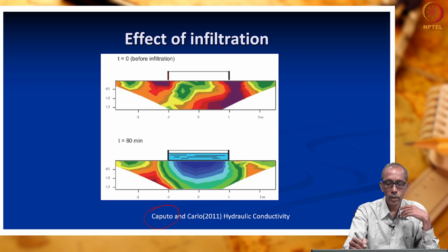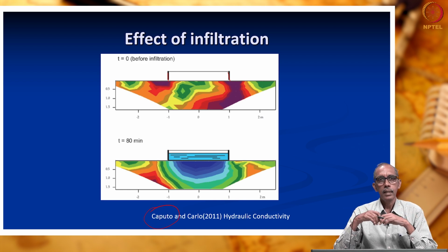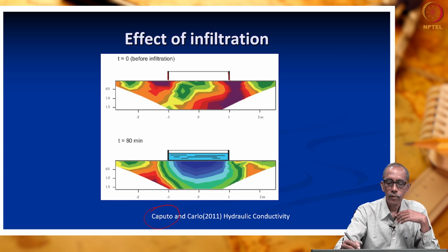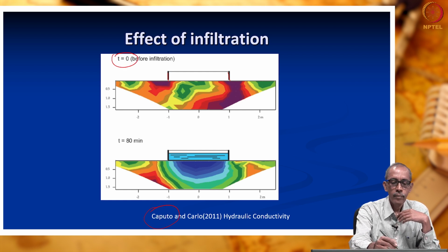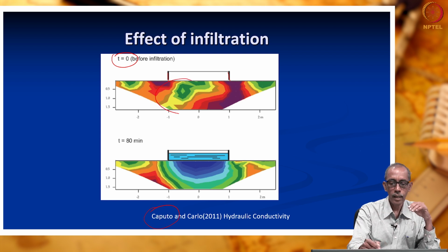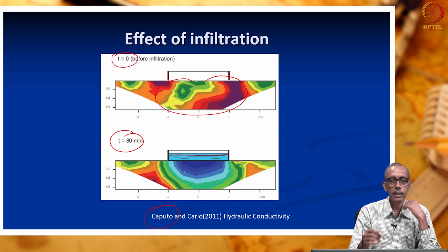So, here is a percolation pond of about 2 meters by 2 meters, wherein a resistivity survey was carried out at different times. Just before filling up the percolation pond, a resistivity profile beneath the surface was obtained. Then after some time gap, after the pond was filled, after 80 minutes, the survey was repeated.